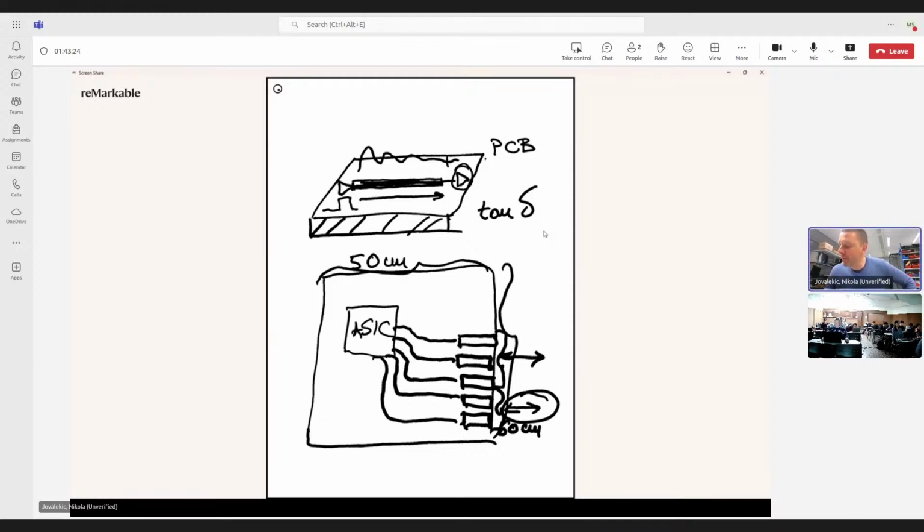The amplitude of the pulses which were sent by this ASIC here simply decreased so much that this receiver could not decode it and convert it to the optical pulse. This also was the case, and these were not. So attenuation here was not enough to decrease this amplitude and to make it useless for these three.